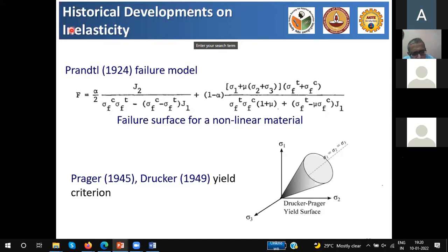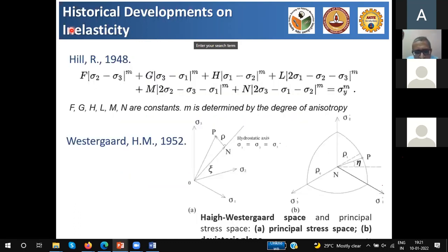determining the yield surface. And therefore, if you have a higher mean hydrostatic stress, then you will have to do much more work to reach the yield. And this is a very important concept which is again being debated today in terms of the multi-axial role of hydrostatic stress and constraint effects in yield of material. So what is being debated today was visualized and postulated in the form of a model way back in the 1940s and so on. So these are the developments. I will quickly pass through these things so that we have more discussions.